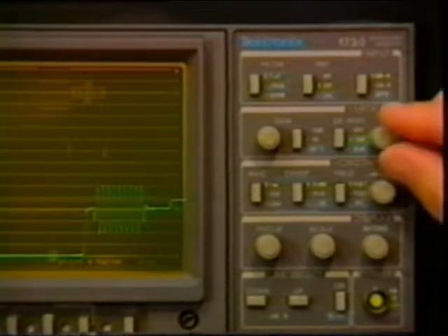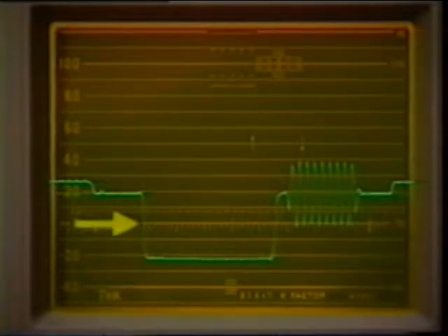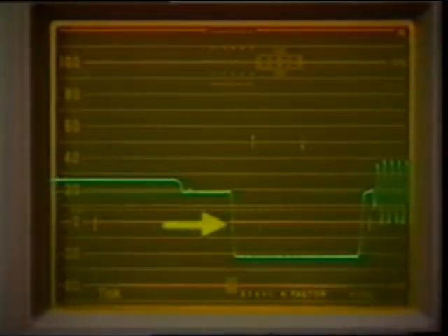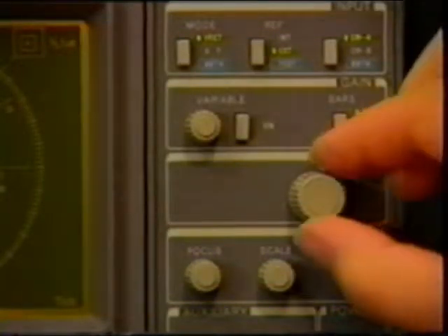Using the waveform monitor's vertical position control, move the sync pulse leading edge so the halfway point falls on a graticule marking on the horizontal axis. Use the horizontal position control to place the leading edge of sync on a major timing mark. It should look like this. This position will serve as a reference point for all other inputs. Now, use the Vectorscope's phase control to position the color burst at 9 o'clock. Remember, don't adjust the waveform monitor or Vectorscope controls.